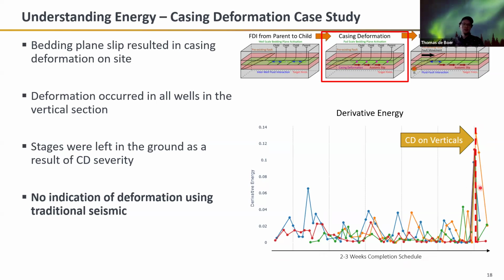And this spike occurs across all of our wells. So if we think back to what I was saying earlier about this cumulative deformation process and this understanding of the reservoir as a system, we can see here that there's a unique type of response that's occurring where all of our wells in tandem are showing this larger than typical energy release. And this did correlate to some stress state changes that were measured in post.